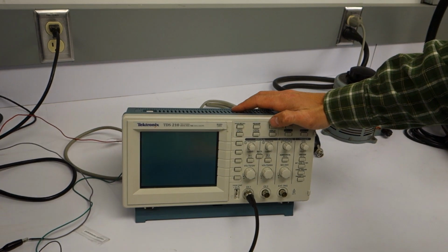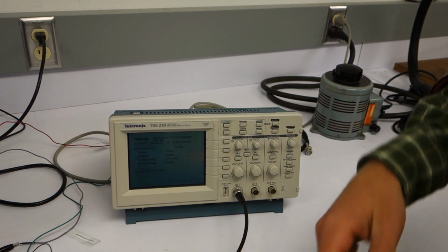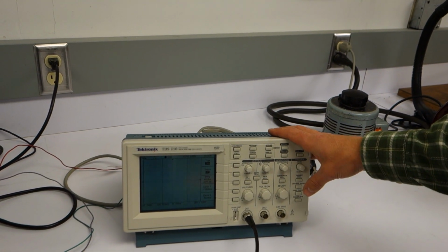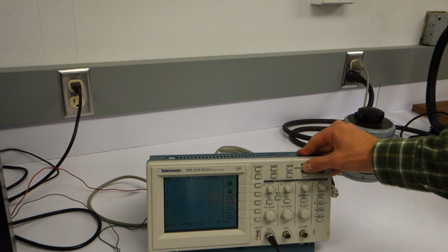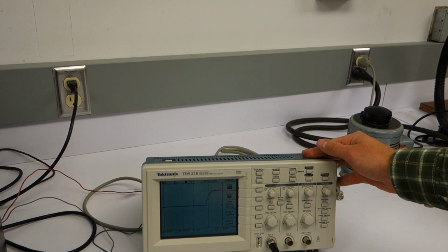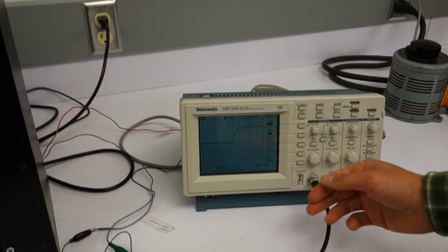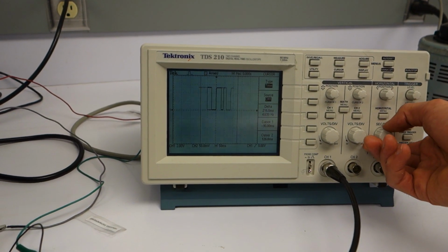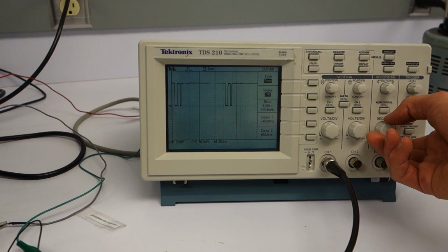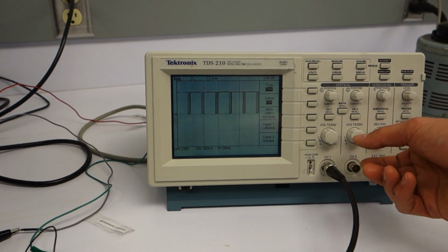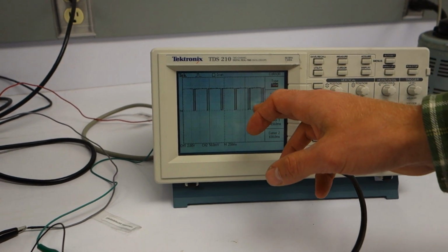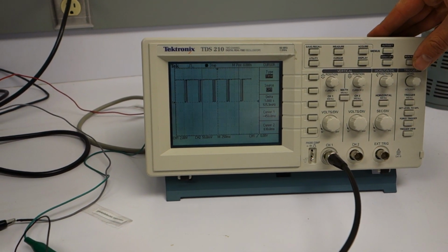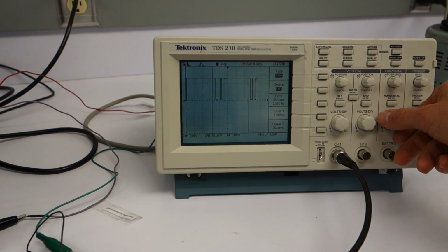And we're going to try to read via the oscilloscope the period of rotation of that turntable, and from that period we can get the angular velocity. So my first thing I'll do is press auto set just so I can see something. And the oscilloscope picks up transitions, so I'm going to zoom way out because I don't want to see the transition, I want to see the whole signal. And I want the period of these signals here. So I'm going to let it go and I'll press run stop to stop it, and then I'm going to zoom in on one of them.